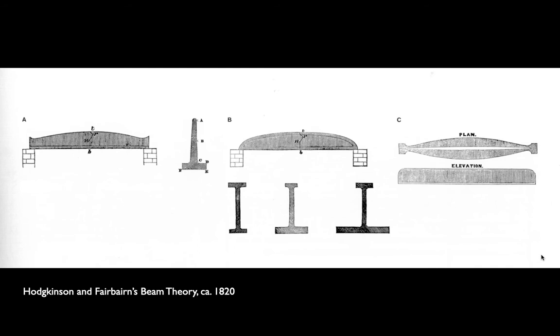And if you look closely, you can see that the top flange, the one in compression, is about, say, 1/6 the area of the flange on the bottom. They test these to destruction, and they look to see which flange has failed first. And they know then that they can do the math backwards and figure out the working stress in tension or compression. They build these beams until they absolutely balance, right? Until the flanges fail at the same time. And that to them is the ideal beam in cast iron.